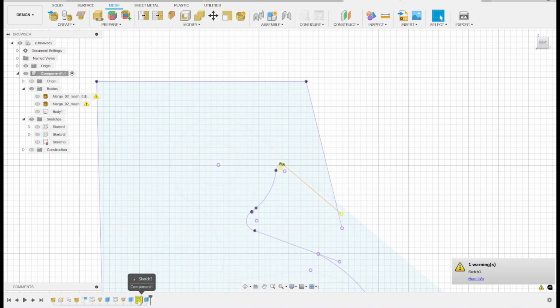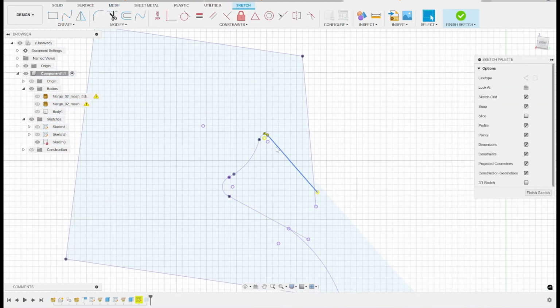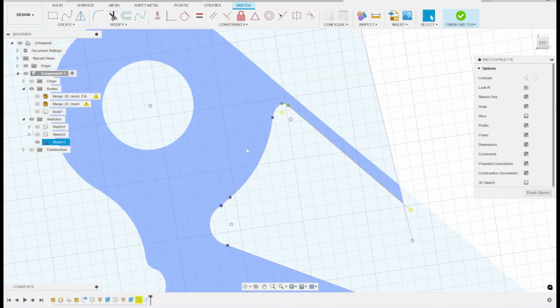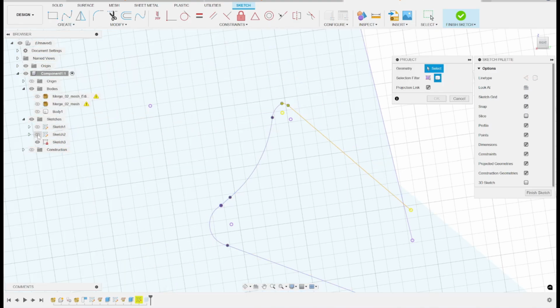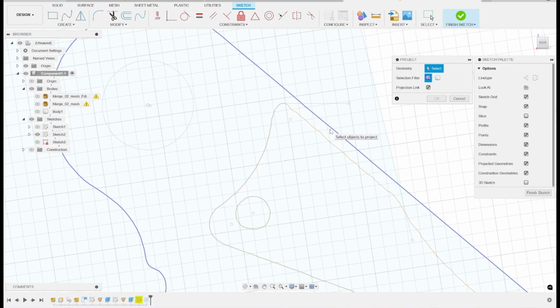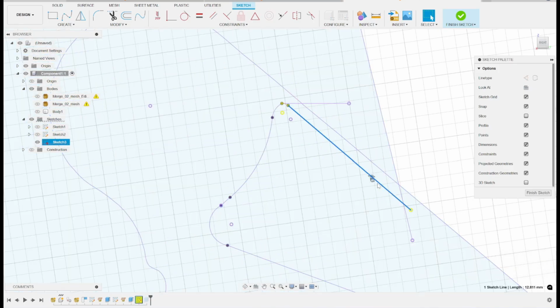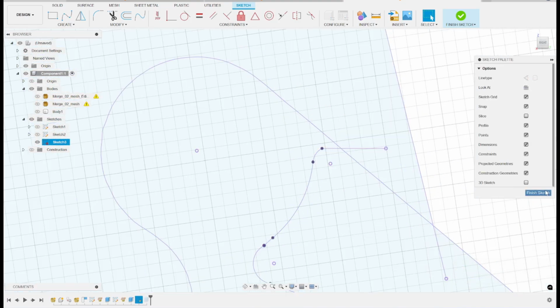Now you're going to get an error about the second sketch because things have changed from the projection. You remove this line here. You remove this line and this one. So what you want to do is do the same thing as projected in. It's from sketch 2. So now it's projected in. We can go ahead and delete this line and that line and finish.